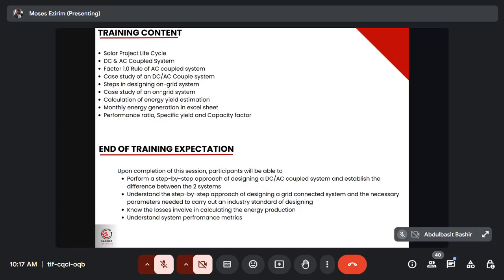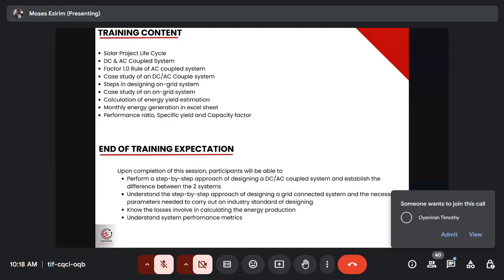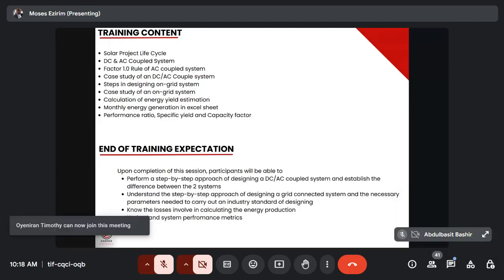Remember the PV case one that I just showed you is actually a C&I, because that is a factory that we want to power. So you can see the area that the client allocated for us, that, okay, don't go beyond this. This is the area that you can do your solar plant. If it is roof mount, once you identify the roof, you still need to carry out structural analysis on the roof to know if it can accommodate all your panels, and that can be done with the help of a structural engineer.